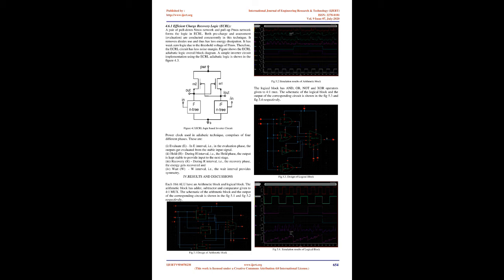When a small amount of voltage is applied to this structure, the capacitor, keeping the gate terminal positive with respect to the source, a depletion region is formed. This depletion region is formed at the interface between the silicon and the SiO2. The positive voltage applied attracts electrons from the source terminal, the drain terminal as well as the N source. This forms the electron-rich channel.